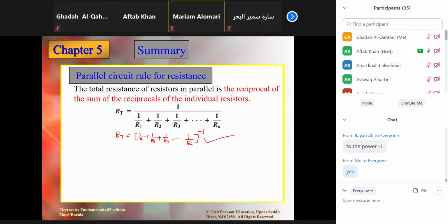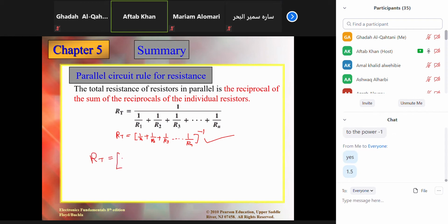So in the previous case, let's try to get the total resistance now. I know the values, so I will just put them in accordingly. So 1 over 680 ohm, 1 over 1500 ohm, I am putting everything in ohms, and another one, 1 over 2200.